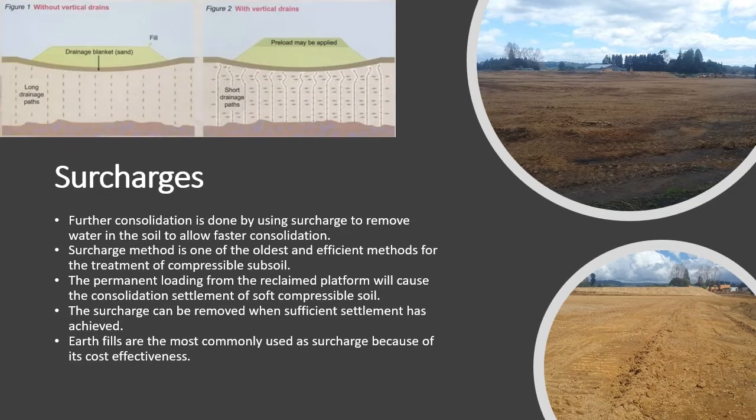The consolidation is the process to drain out water from the soft soil. The backfill represents the load of the structure to be constructed, so that when the structure load is put on the soil foundation later on, the movement of the soil foundation is minimized.